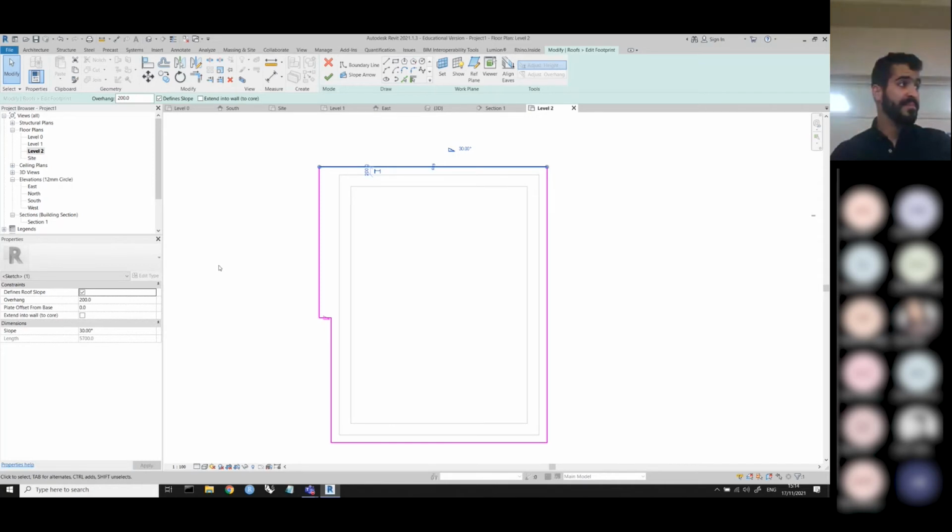You can just change it. Yeah, because you didn't define the slope. So this is what I'm doing here, right? So you select on the edge that you want it to slope. Yeah. So think about it as the edge coming down to your wall with an angle. You select it and then you see, is it sloped or is it not? On the tick box on the properties.